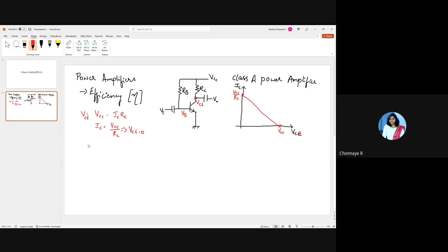Let us take one simple common source amplifier, okay? Since we learned it first, I assume that this will be much easier for you to relate. So now here we are going to give some DC voltage VG and some DC voltage VD so that this is operating in saturation. Correct? So that it can be used as an amplifier. This you are able to understand.